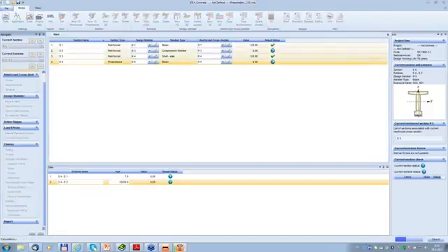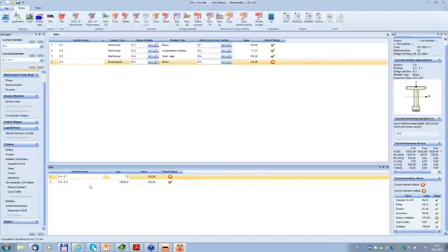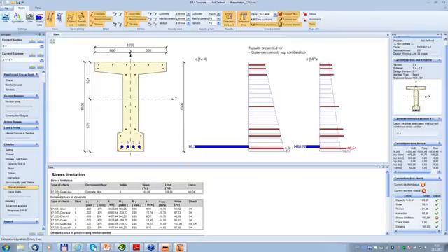This is already done. There are hundreds of reinforcement bars, so it takes a little bit longer. Now it is finished, and now pre-stressing, and you see this extreme is not satisfactory. We see that the stress limitation is 4% more. We go to stress limitation. We see the response, and the program tells you the provision 6.23 for quasi-permanent combination, sub-maximum of pre-stressing reinforcement, concrete fiber number 6.